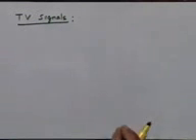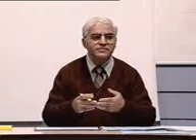The TV signal is a moving picture signal. So when it is a moving picture signal, you have to make sure that you don't lose the essence of motion itself. As I said, you first have to convert this into an electrical signal, which is done through a TV camera, which, through an optical lens system, captures the picture, converts it into an electrical signal, and scans that signal line-wise to convert it into a one-dimensional signal.